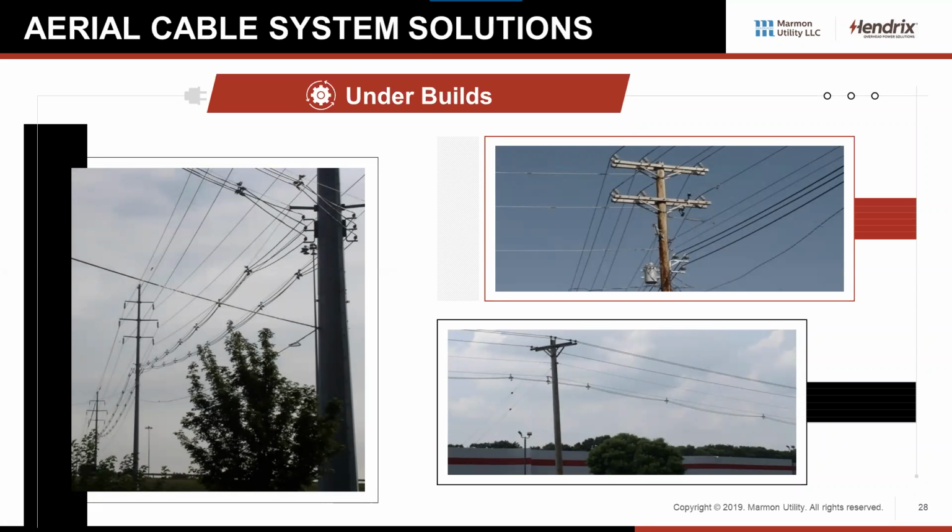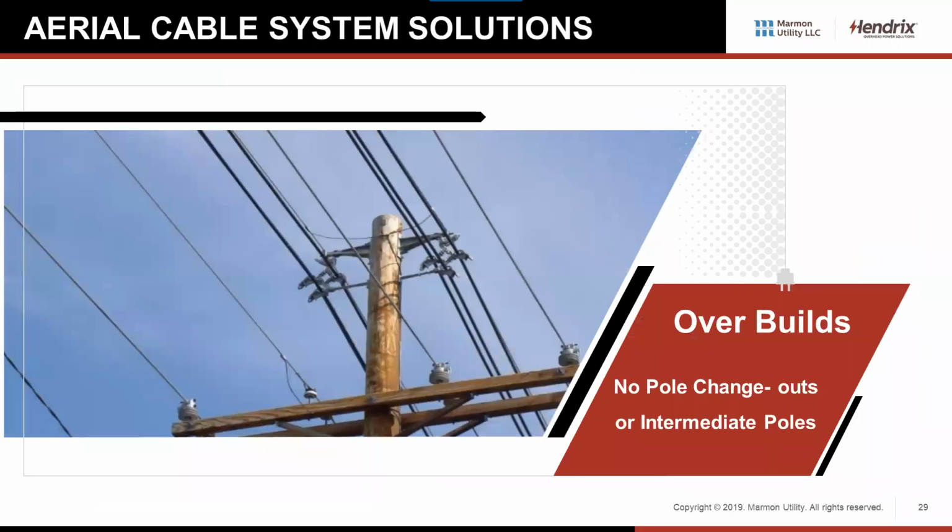Underbuilds, I already touched on this a little bit as well. If there's enough capacity available on the existing poles, this is a great way to use existing infrastructure to get some distribution or even some more transmission circuits installed. Express circuits, anything like tie circuits between substations.